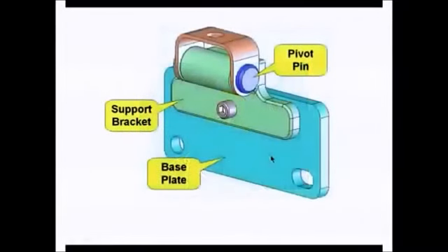Steve Eccles, a principal design engineer for Honeywell's Turbo Machinery Systems division, suggested the topic for this month's tip. Steve and I are both irritated by the people who think the primary datum feature for a hole has to be the surface that is perpendicular to the hole. Let's take the support bracket as an example.